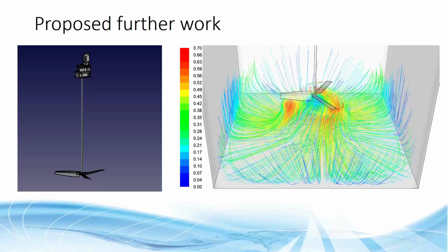I discussed with other engineers within the company who have worked with other distribution chambers and other flocculators what solution they think for this specific scenario would be suitable. We came to a conclusion that there would be different methods. One could be to insert more benching into the chamber, so reduce the volume overall, which will increase velocities.